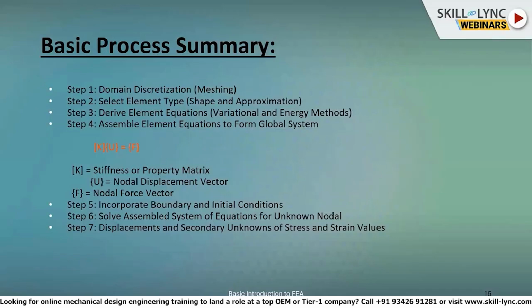I also want to tell you the steps briefly, in other words. The first step will be discretization. The second step will be defining the global displacement vector U. Then define the element properties and material properties. Fourth will be to compute the element stiffness matrix. Fifth will be to compute the singular global stiffness matrix.